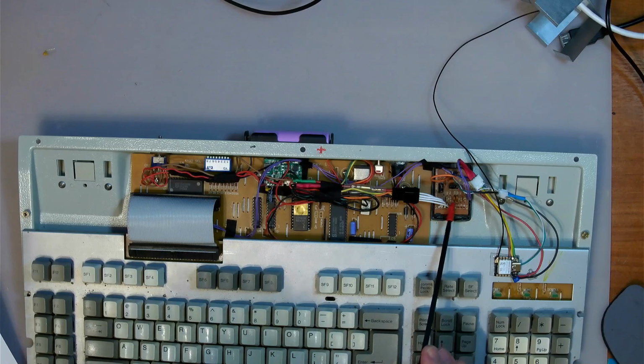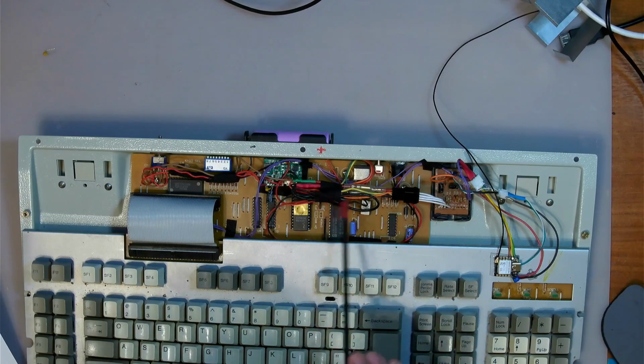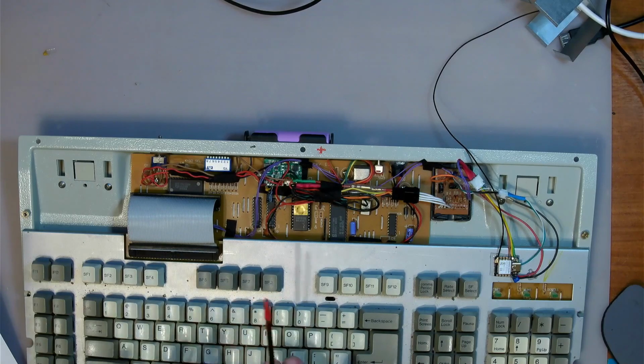And so then I started to backtrack, and I disconnected this thing here and picked up the clock and the data signals on the oscilloscope, and I noticed that the clock and data signals were being held low, and normally they are high when it is inactive. And if I hit enough keys over here and did some fiddling and so on, occasionally I saw a little blip there where it would go high, then it would show a little bit of data there, and then it would go low again.